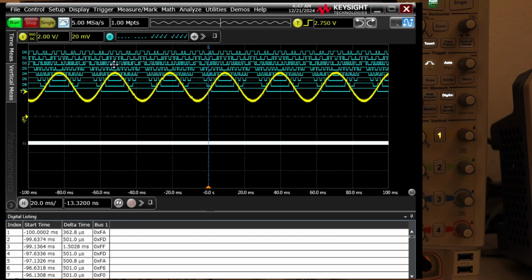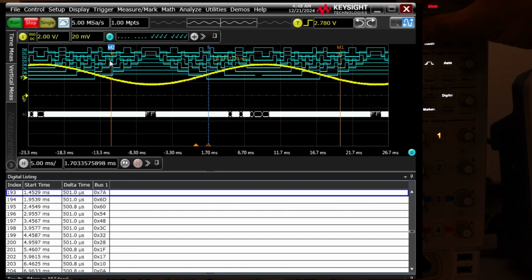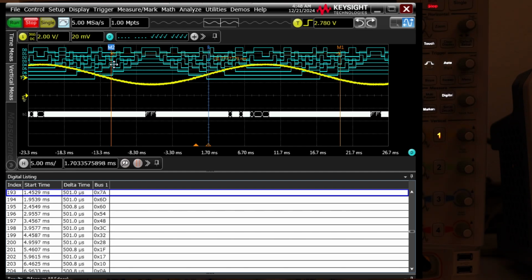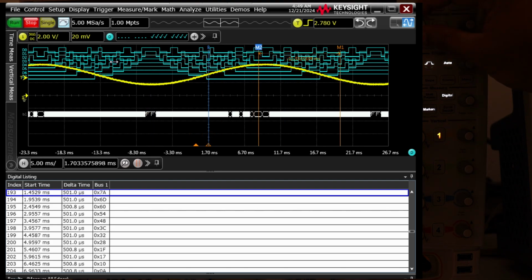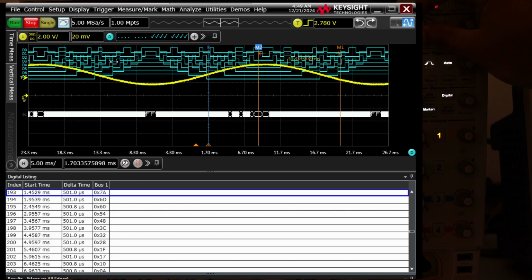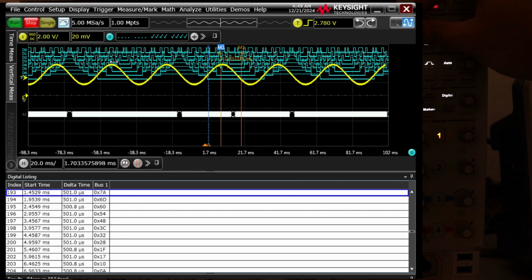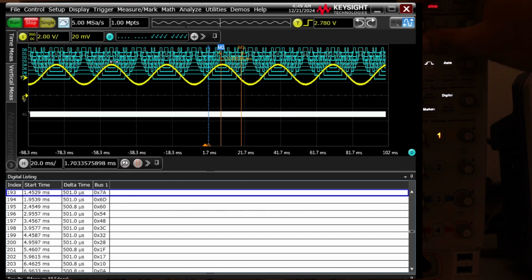And now let's zoom in. So we see the bus is decoded, or the displayed value is available, and you can see already where the value is at highest. Right here where the cursor is, it shows FF, and where the value is lowest, it shows again with the cursor there. It's supposed to be just 1 or 2 or 3 value. Yeah, so that's correct. So our whole bus is being displayed. If you want, you can trigger on it or do whatever you want, and that's very easy to set up.